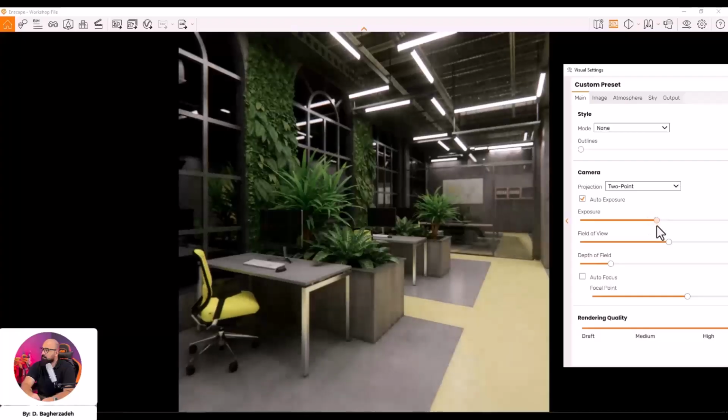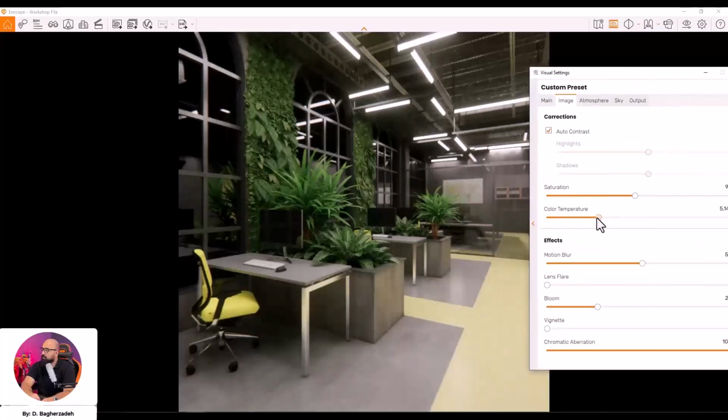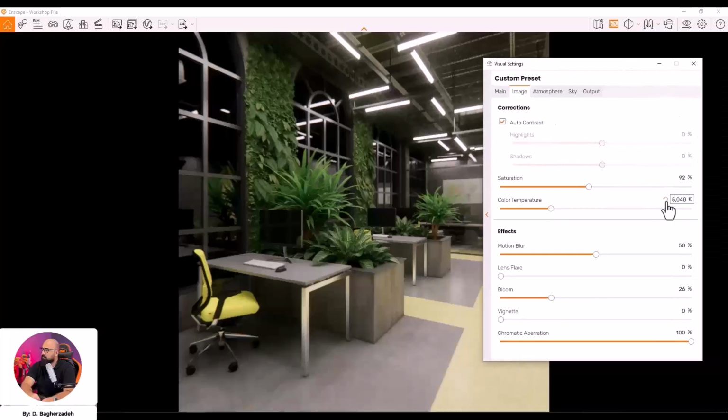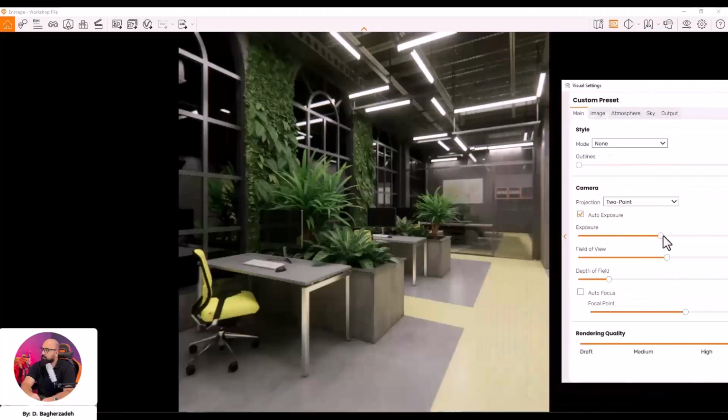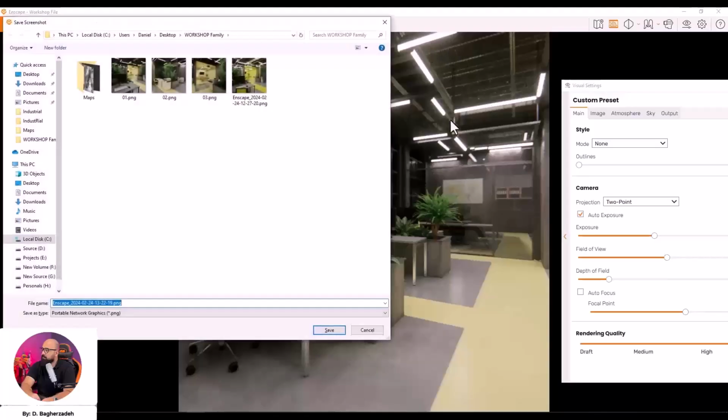Then, maybe, just maybe, a little bit more exposure here. And also, let's increase the temperature. What if I reset this? No, this isn't good, actually. So, yeah, let's increase the temperature. Reset again. And let's reduce this from here. And then again, increase the temperature a little bit to make the colors more realistic. And I guess we can even reduce the exposure a bit more. Okay, we have a pretty good angle here, and the light sources are set here quite nicely. Let's go ahead and create our render now.